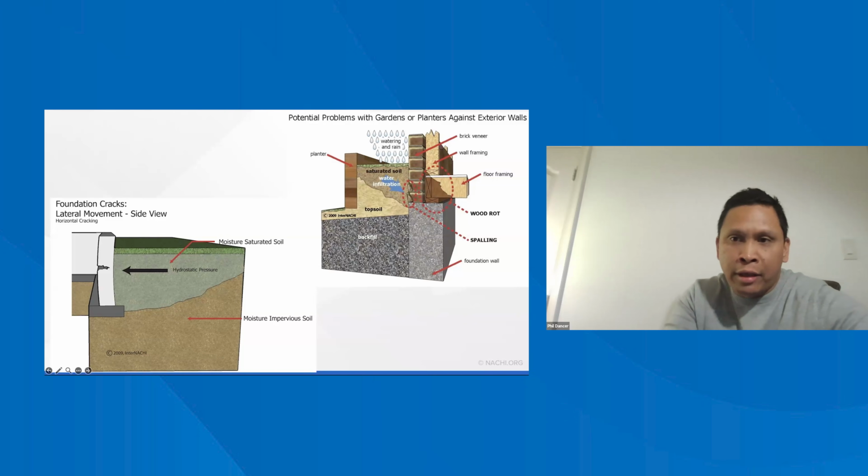The other one that I think is also worth noting, if you're inside the basement and it's an unfinished area, if you see spalling on the actual wall itself, so flaking, that's a sign that there might be water or moisture hanging around the exterior of the home and the foundation. And if you didn't see any signs and note that initially on your initial walk of the exterior, go back outside, because there's most likely going to be a condition that explains the reason why there's spalling there. We've got to direct the water away, and it's not being directed away enough.